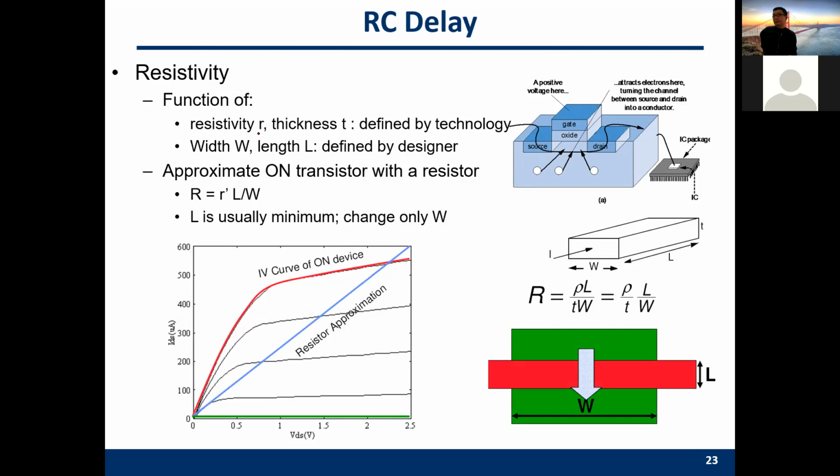So the resistance of the gates is proportional to the transistor length and the transistor width. That's the reason different process technology like 65 nanometer, 10 nanometer have different resistance and capacitance. And here is one example of how to calculate the resistance of the transistor by this equation.